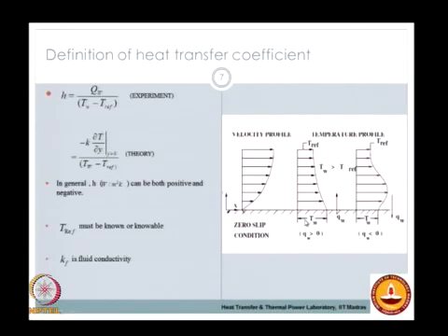where you apply, for example, a constant isothermal temperature boundary condition to the wall. In one case, on the left, you see a temperature profile like in the case of a flat plate flow, where you see a continuous decrease in the temperature as you increase the y distance.